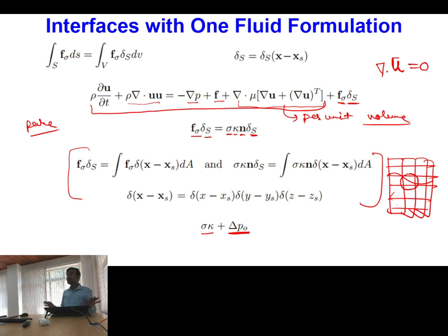But the major indication is, when we use the one fluid approach, then my momentum equation majorly remains the same as that of the single phase equation, but one additional surface tension force we add in terms of the body force. But in that body force, we use some mathematical operator which indicates its applicability only at the interface. Okay, so this is how one fluid formulation can be actually employed. So this is nothing but the complete basis for all the one fluid formulation based methods.